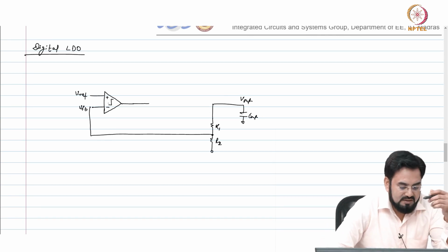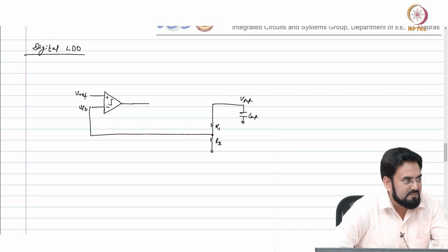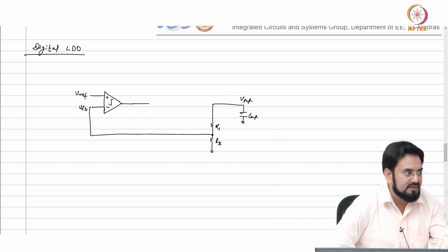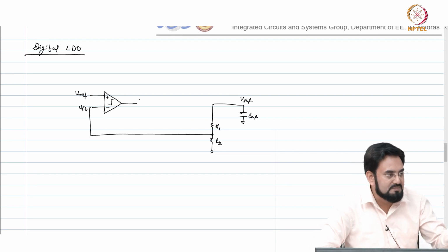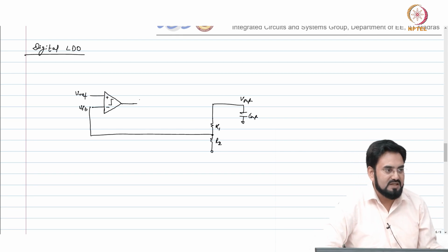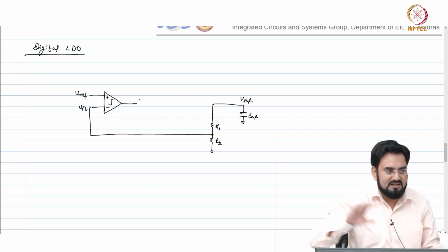If you don't want to do that accumulator, then use a flash, but depending upon the resolution you require that many comparators, 2 to the power n minus 1, that will bloat your area. So that's why I was saying you can make it as complicated as possible depending upon your requirement. If you need it very fast, you just use flash and that will do your work.